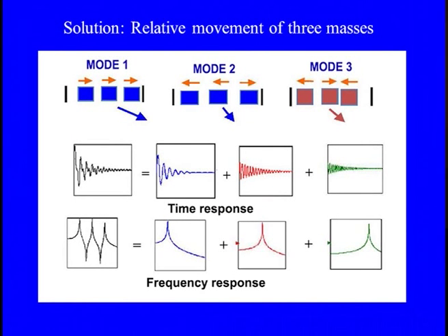So, this is the basic modal feature of these masses, and due to that we can get excitation of different levels in the time and frequency domains. In the time domain, the overall picture is time with displacement variation or time with acceleration variation, and it is a combination of the first, second and third displacement features. But one drawback of the time response is that, though the masses are in relative displacement positions, we cannot find the exciting frequency. For that we need to go to the frequency domain.